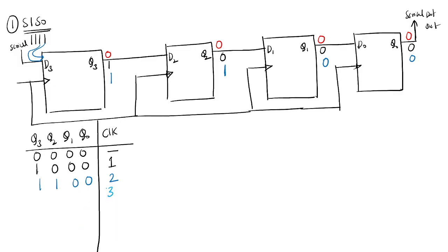So that is a shifting operation. Normally this will be shifted, this will come to this side, and the loading operation will be done. At the third clock pulse, what happens again? This 1 will come to D3. So whatever D3 is, that Q3 will come, and this one will come here, and this one will come here, and next this is 0 only.